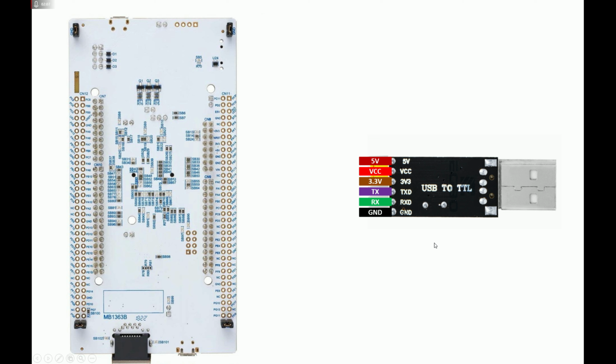So guys, let's do the connections. Now to do the connections, you need to select a UART port. Our microcontroller has over 9 UART dedicated hardware ports. So I'm going to use UART4, and UART4 is assigned to 6 pins, 3 TX and 3 RX. You may use any pair like PC10 and PC11, this is one pair, PA0 and PA1 is one pair.